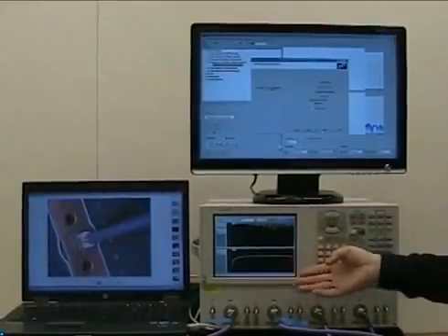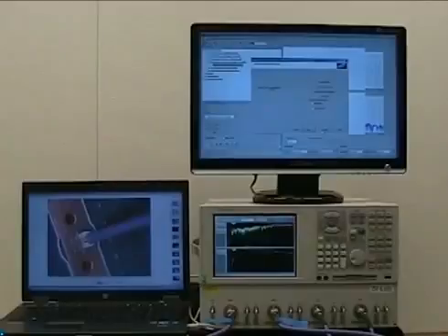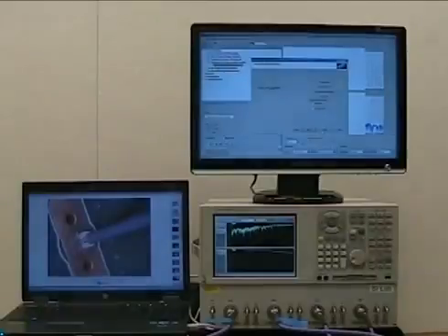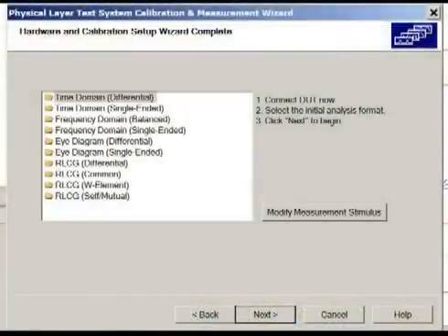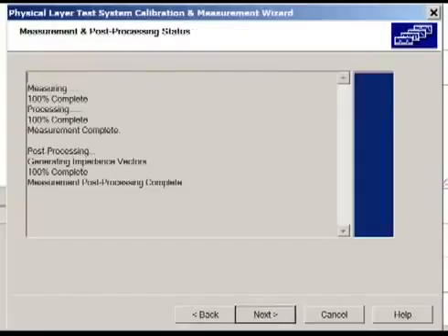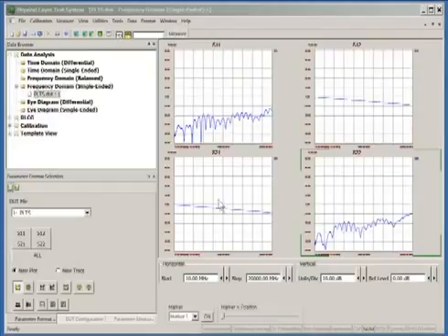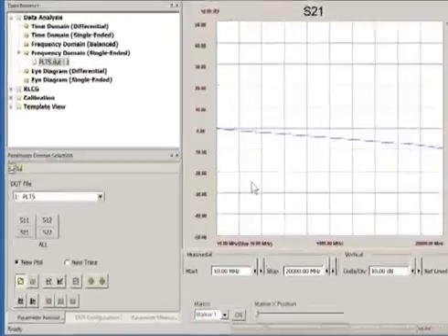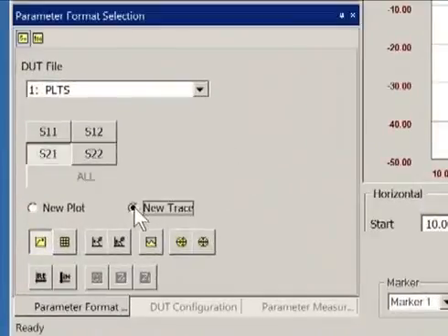Here we have an open, and as I land the probe, the connection is made and we have contact. Now we can proceed with the actual measurement. Once the electrical connection to the 2x through PCB structure has been verified, then PLTS can finish the measurement and import the data. A quick look at the frequency domain S parameters shows the expected low loss and minimal reflections